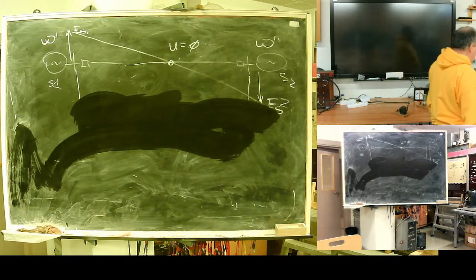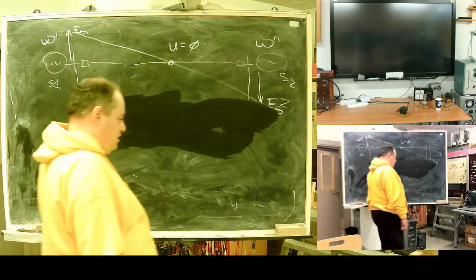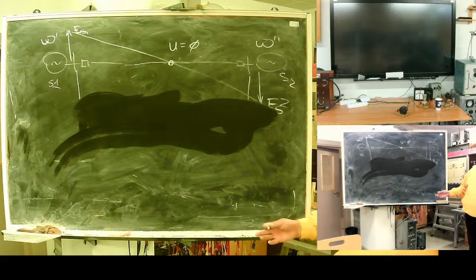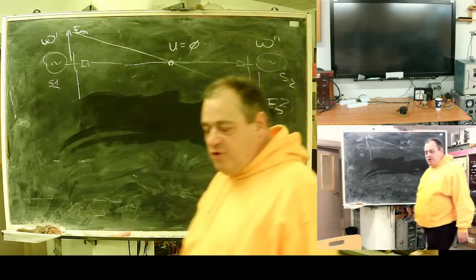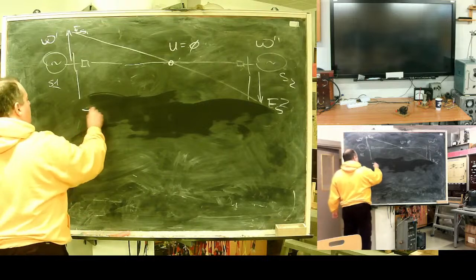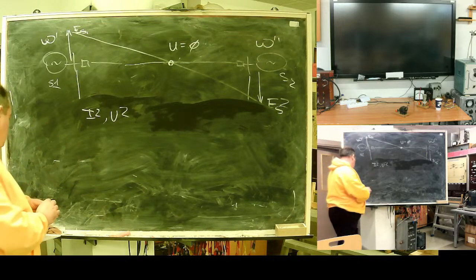during power swings. Only super advanced devices, not existing, they're theoretically possible, but I didn't see anyone, how to say, in the flesh, that can operate during power swings. But a simple industrial protection, from the shelf, will be locked during the power swing. Older versions relied on a combination of negative sequence parameters. This scheme is not very reliable.